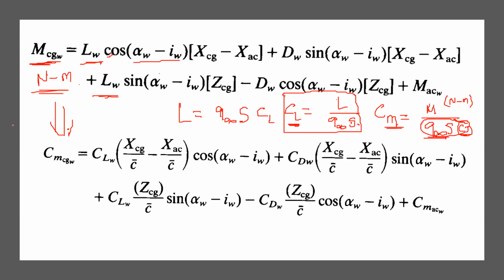So when we divide this entire equation by dynamic pressure and we convert these actual moments into coefficients here, the C bar is appearing here, if you can see that. In the earlier equation, there was no C bar, but the C bar comes because we divided by C bar also, because we are non-dimensionalizing the moments and forces. All right. So the difference between these equations is nothing but the non-dimensionalization.